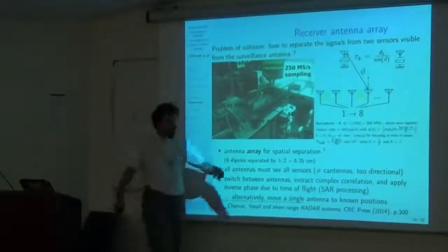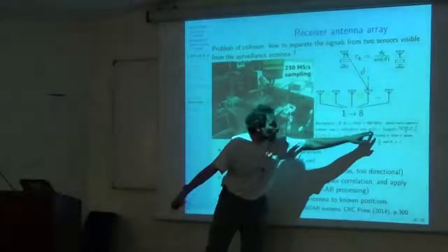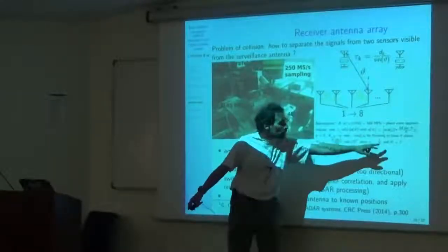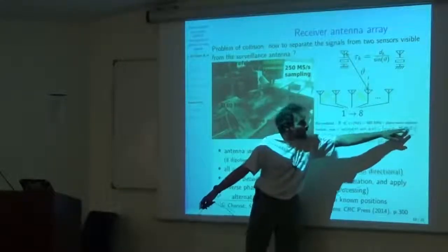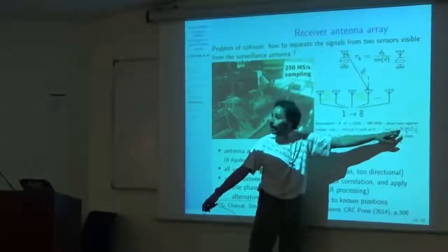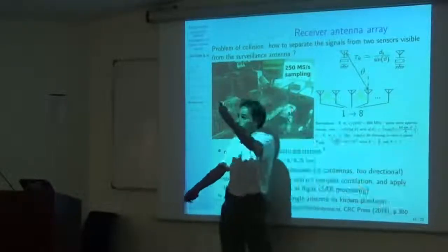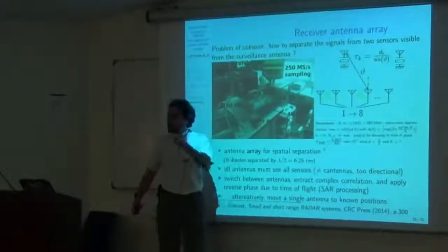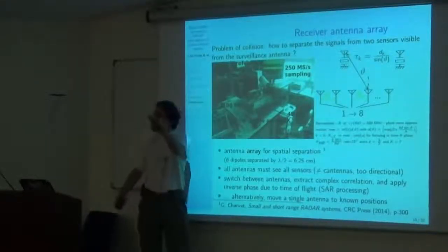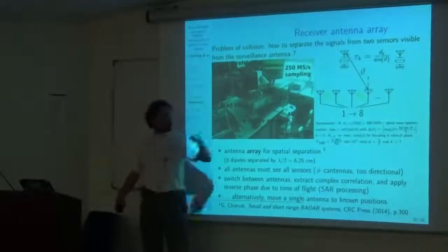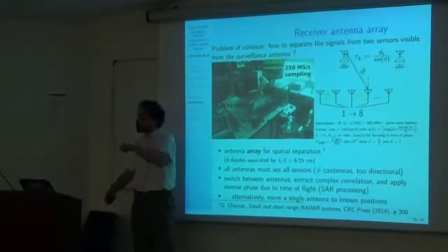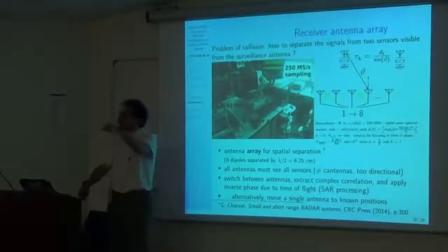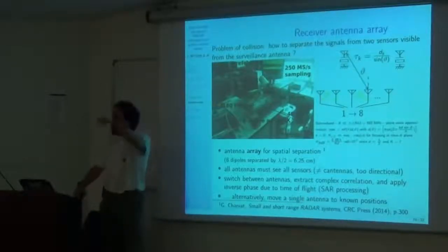So you just take this phase artifact here, which is only dependent on the distance between antennas, angle of arrival, and antenna index, and that tells you the wavefront direction of arrival. So you just need to collect each antenna one after the other, and then you do the processing on the matrix that was generated. On the x-axis you have antenna number, on the y-axis you have all the samples as a function of time.